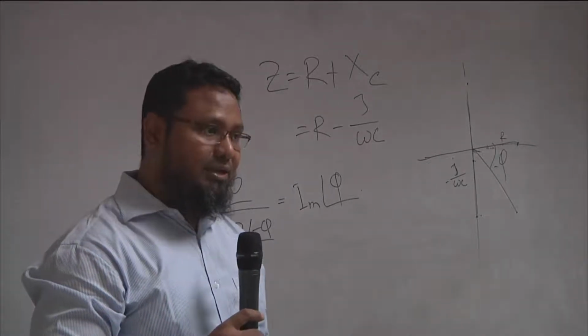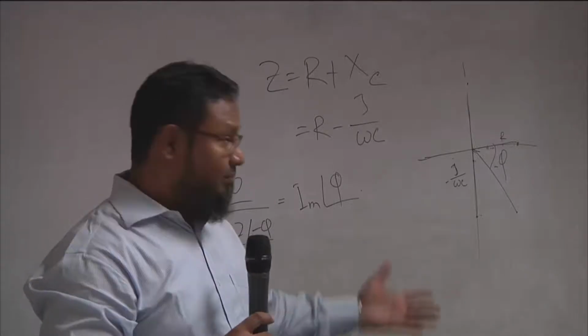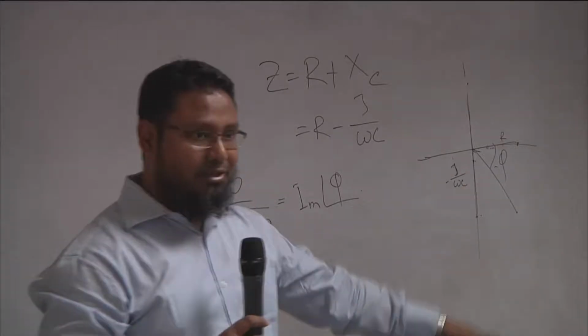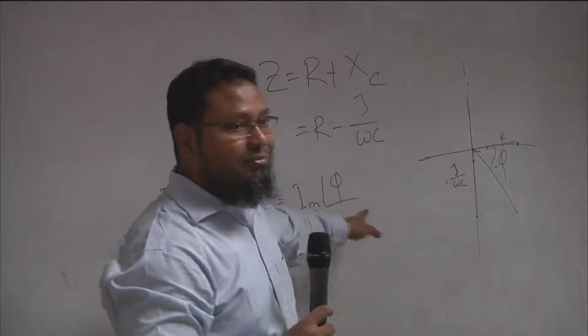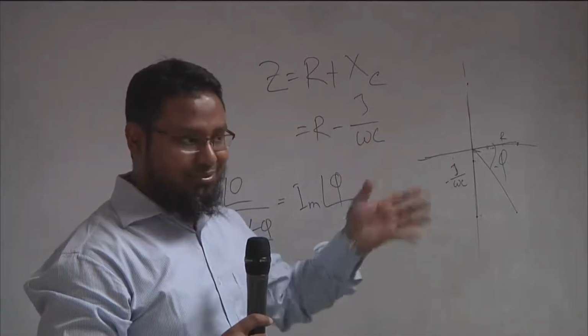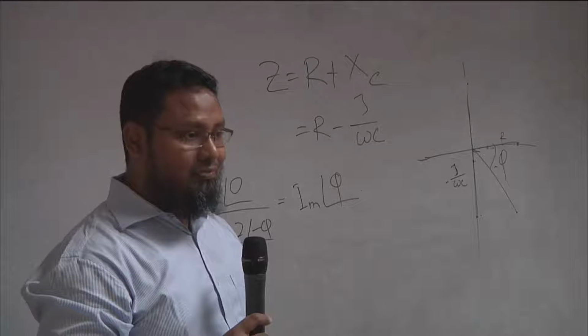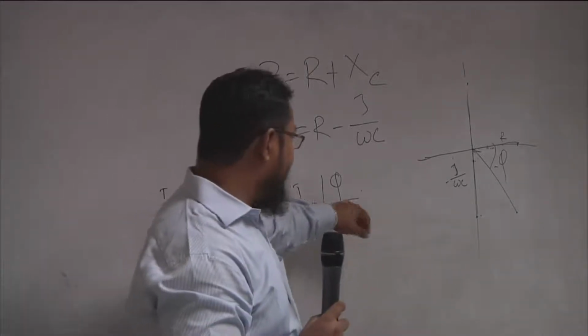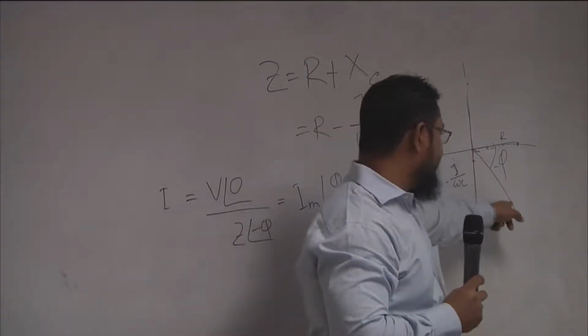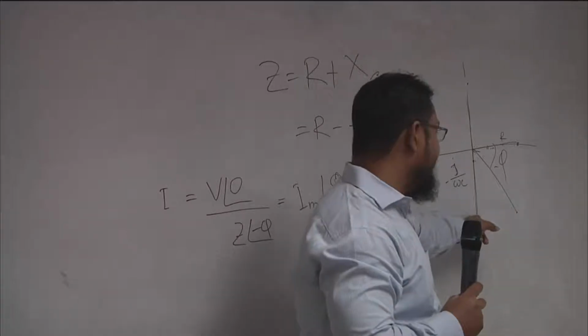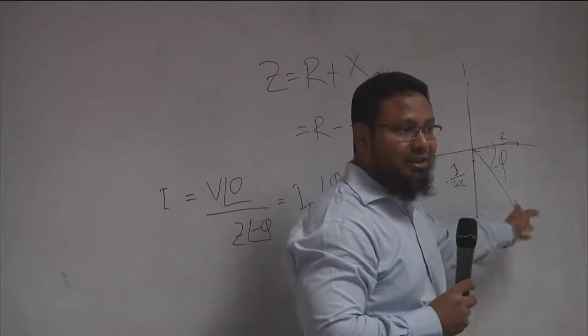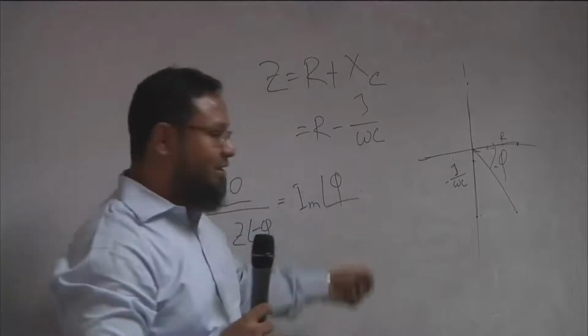Obviously, you can see the current will be leading the voltage by a certain angle because it's capacitive. If it's entirely capacitive, in other words if there was just a capacitor, this lead angle would be 90 degrees, going back to the capacitor voltage-current relationship.